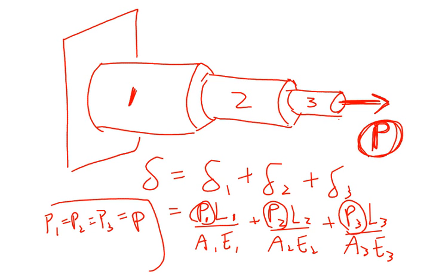They're all equal to that external force P, then that would actually be incorrect. P1 and P2 and P3 are the internal forces in each of rods 1, 2, and 3. In this particular problem, this is so simple, those internal forces do happen to be equal to the external force P. Okay? But it's not always going to be like that. All right. So let me talk a little bit more about this idea of internal forces.